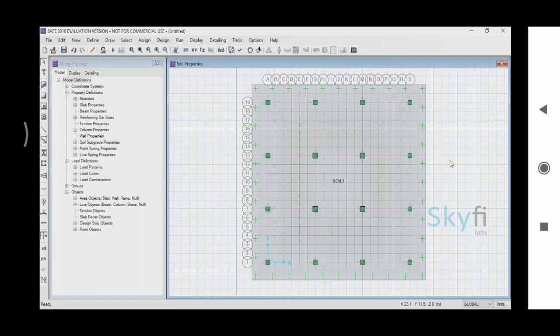You will now assign the loads on the column centers. Here the loads at each of the 16 points are different. So you cannot select the points together, but individually apply the dead and live loads in each point. Select the first point for column 1. Verify each time in the bottom left corner that one point selected is mentioned.